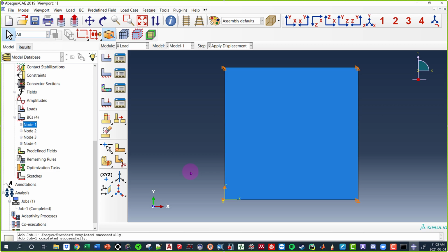But keep in mind, and this is one of the things too, your matrix is symmetric, right? The stiffness matrix is going to be symmetric. So once you're getting into the later stages, you guys don't actually have to look at all 4 of the nodes. You just have to make sure that you are getting a nice diagonal part of the matrix, and then the other part you just say is symmetric. Nice and easy. So please don't do more work than you should.